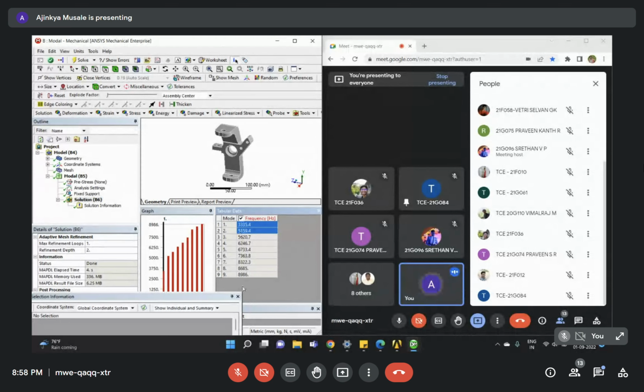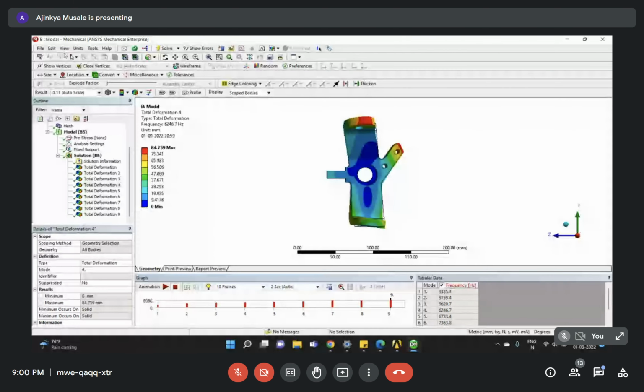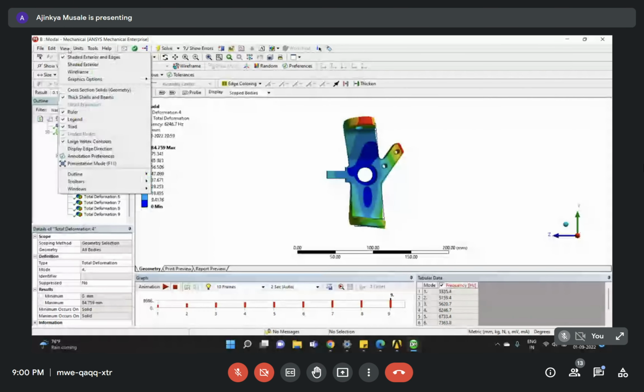There is one link: just go over here, in the view tab, there you have the option of windows, and there is one option to reset your layout. Just click on that, and it will be back to a neat and clean window. Fine, so this is important. I'll tell it again. If you have made some mess over here and you need to go back to the original window size, go to view, go to windows and simply click reset layout. You will get a nice and clean window again.